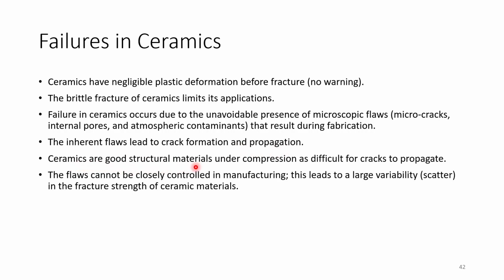Ceramics are good structural materials under compression as it is difficult for cracks to propagate. So if you are compressing your material, your crack is not likely to propagate. The flaws cannot be closely controlled in manufacturing, which leads to large variability or scatter in the fracture strength of ceramic materials.